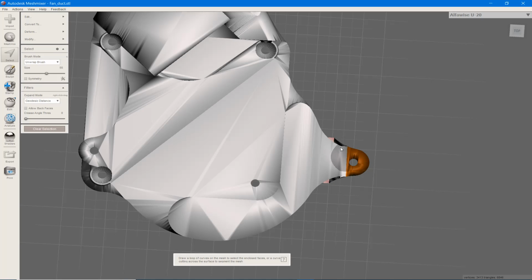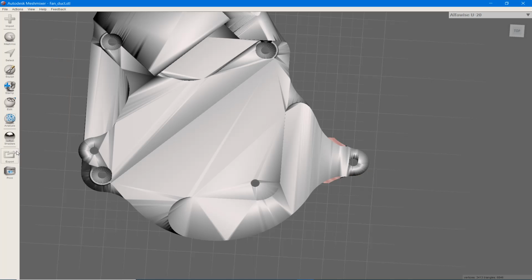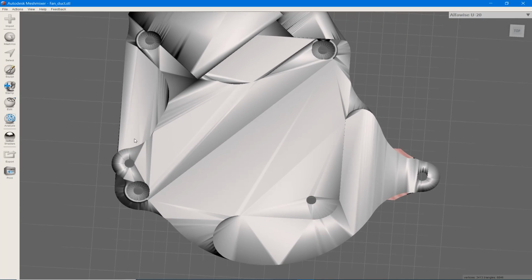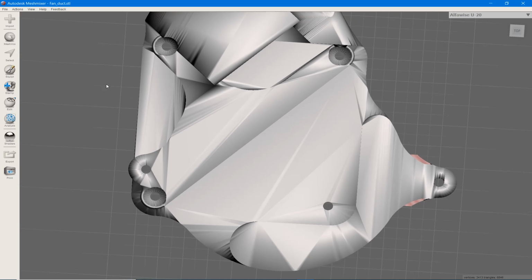And now you notice I have now brought that hole, and just that hole, out 1.5 millimeters. And I'm going to hit escape to get out of it. And now I want to come to this hole. And this hole's been a bit tricky for me. I managed to do one where I got it really good, but I'm not going to waste a lot of time because I'm just trying to demonstrate how this works.